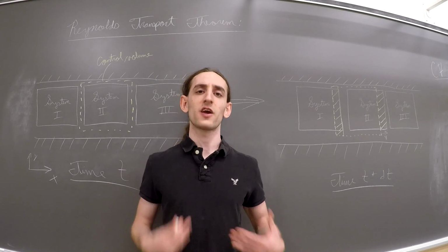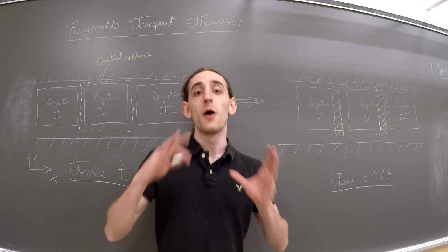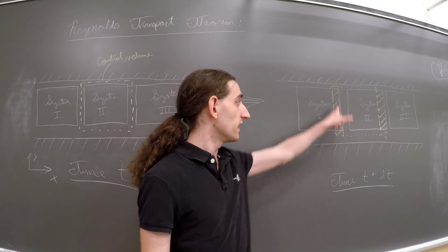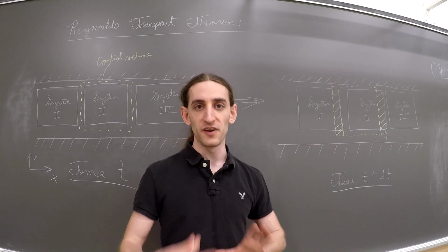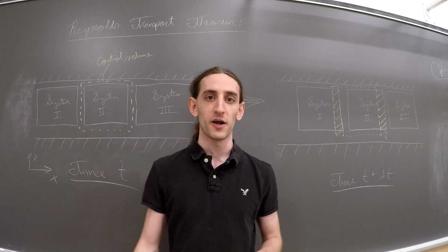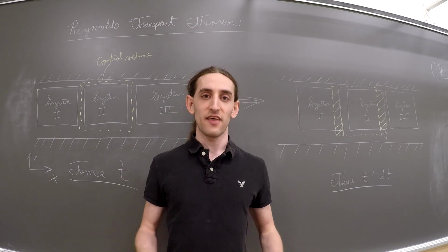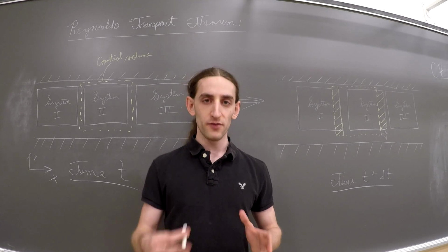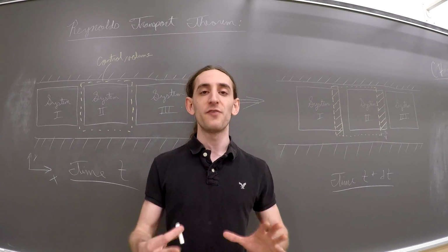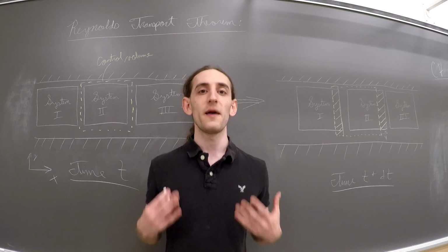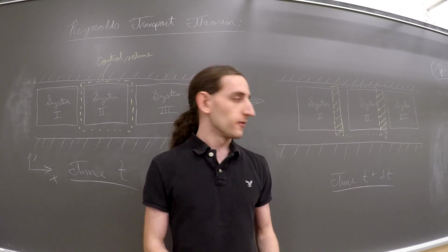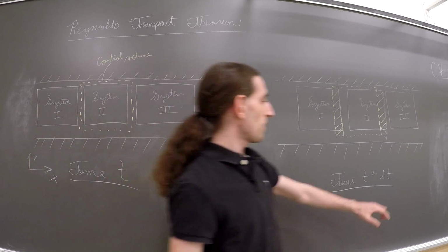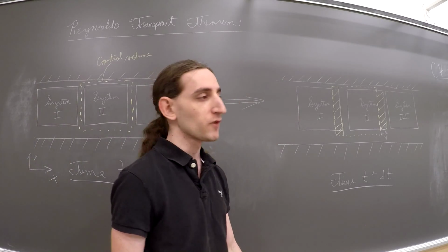So now that we know how to compute the total amount of fluid property B in a given region, in addition to the fluid properties in the flux region, basically the region that is being fluxed in or out of our control volume, we have all the ingredients needed to derive the Reynolds Transport Theorem. Before we do that, we're going to figure out the total amount of properties in the systems and the control volumes at time t and time t plus delta t.